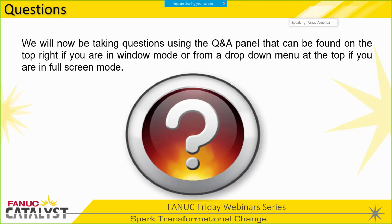not. Another question here: is the Plus software GPM faster? Yes. With R30iB Plus, probably a lot of you haven't had a chance to use it yet. As you saw in the screenshots and my demos, the interface is different, and the CPU on the R30iB Plus controller is essentially the same CPU, but it's faster. It's a faster clock rate or whatever. So yeah, the GPM is about 20 to 30% faster just in raw times.